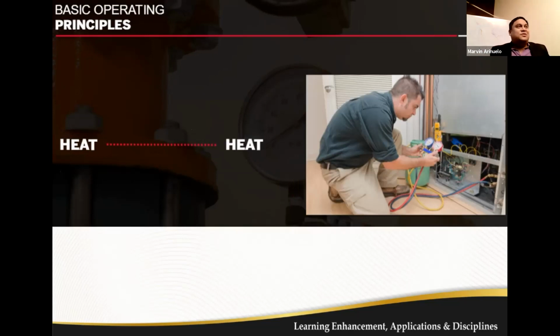All refrigeration systems are considered heat exchangers, meaning the system takes heat from one space and transfers it to another. So like here, let's say there is an FCU. Actually, the evaporator absorbs the heat of the room, and in its place supplies colder air. On the other hand, an outdoor condensing unit is actually heat rejection, meaning it rejects heat to the atmosphere. That's why the evaporator is inside, because it's a form of heat absorption, and the condensing unit is outside, which is heat rejection. In a colder country, maybe you consider a reverse cycle. No need for a condensing unit inside; directly a heater, not a heat exchanger.